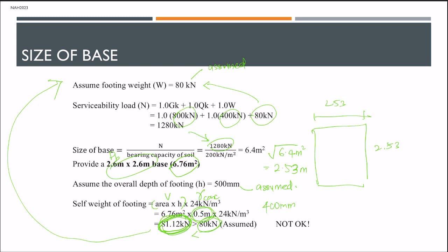However, if you still remember, we did a preliminary checking for shear. Sometimes if the depth of our footing is too low, we are worried that the preliminary checking for shear will fail. Therefore, I do not want to lower the height. So, I choose to raise this value.